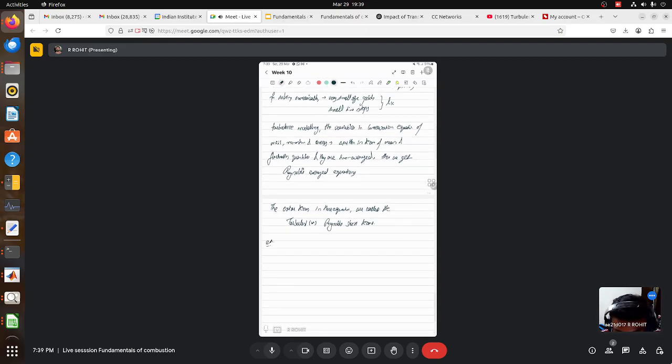So you were shown some example of a 2D boundary layer. From the momentum equation, the initial conditions like rho and u are constant. This was one of your assumptions, and the other one is that the gradient along x is very small compared to the gradient in the y direction.